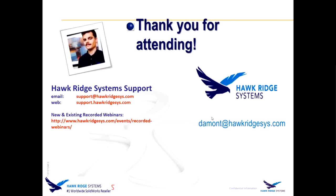However, it's not always recommended because in a lot of situations, you may have a part that is made out of the same material as something else, but it may not actually dampen out the same way because of the shape of the part or how it's attached or what environment it's in. We do also have a different way to handle damping called Rayleigh damping in the nonlinear dynamics study, which does have a material coefficient in there, as well as another term that you can input. So there are several options, and that's kind of the thing we go over in the training class to help you figure out which approach you need to use.